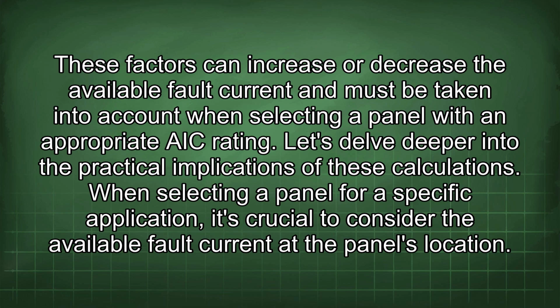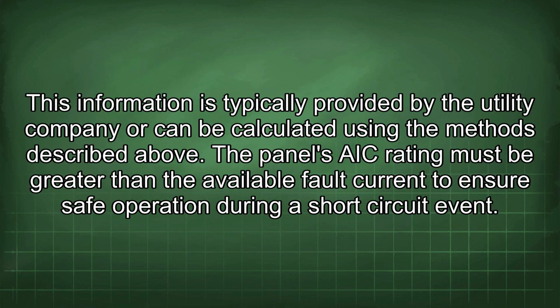Let's delve deeper into the practical implications of these calculations. When selecting a panel for a specific application, it's crucial to consider the available fault current at the panel's location. This information is typically provided by the utility company or can be calculated using the methods described above.